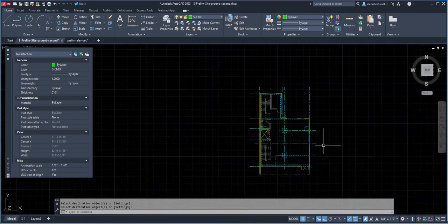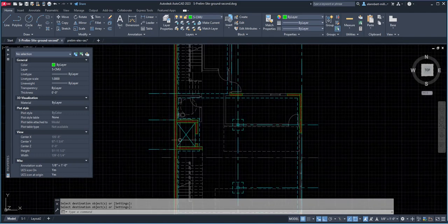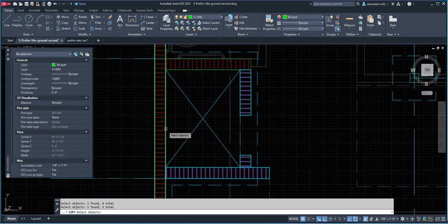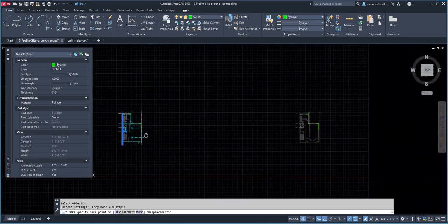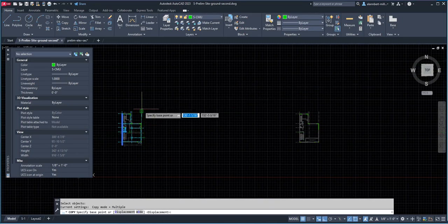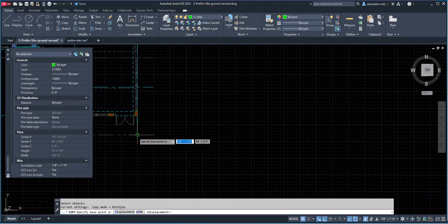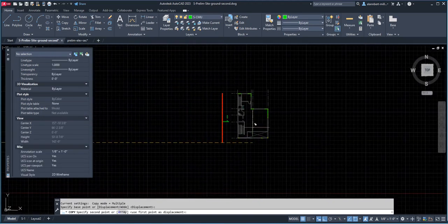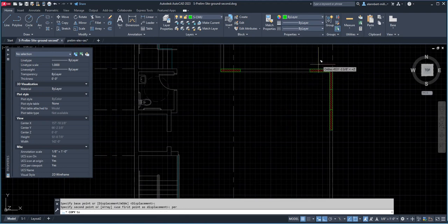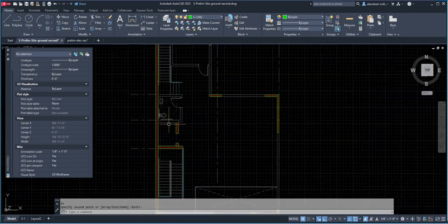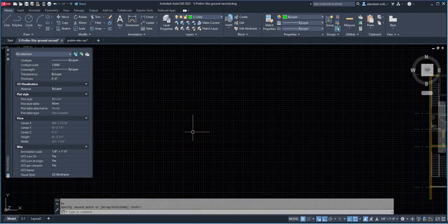And we're going to do the same thing on the second floor. So we're going to simply copy this, this, this, and that one, and this whole long wall section. And we are going to copy from the edge of the corner of our wall here, our property, and then we're simply going to do a perpendicular to a grid line. Okay, and they should all line up. Oh, we missed copying this wall here.